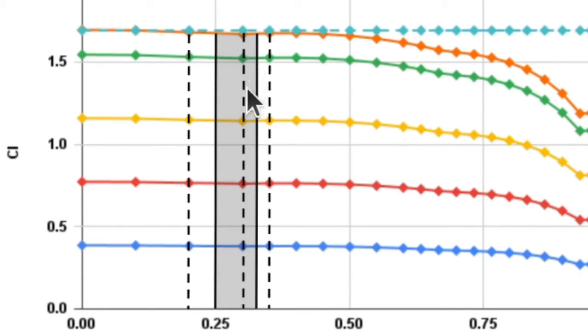So to calculate the area, we're going to take this span, multiply by the coefficient of lift. And then we're going to do that for each of these dots over here and add those all together. And that'll give us the area underneath the curve. Now I did that for all the wings. So let's take a look at the results for that.